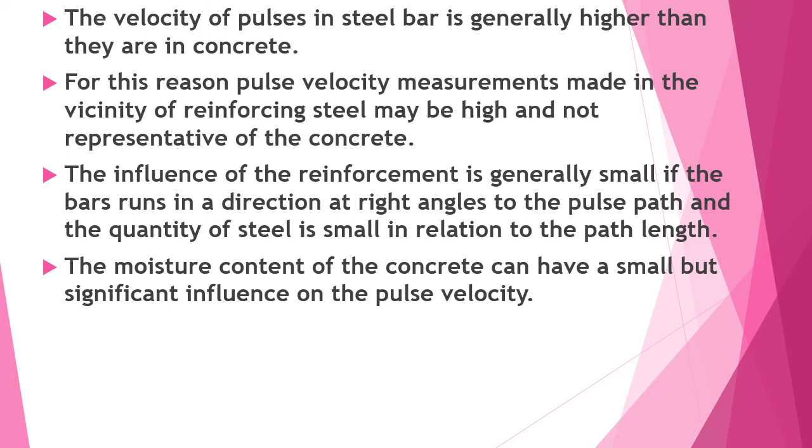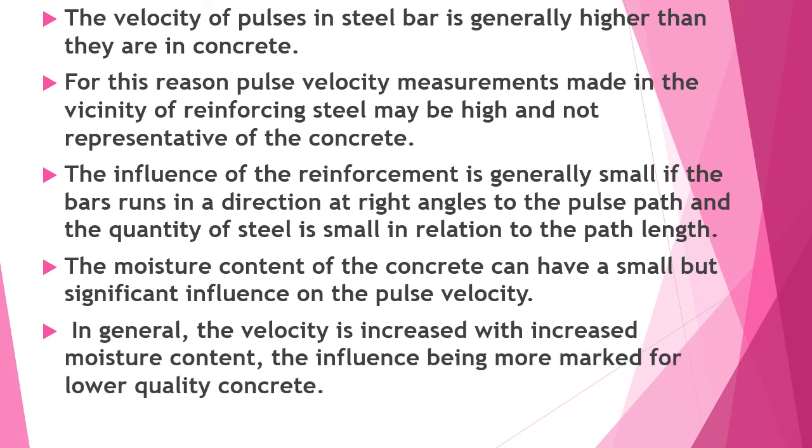The moisture content of the concrete can have a small but significant influence on the pulse velocity. In general, the velocity is increased with increased moisture content, the influence being more marked for lower quality of the concrete.